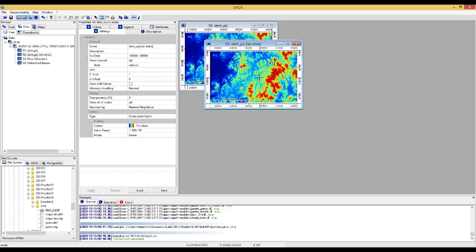If cells with higher elevation surround any cell in a DEM, the flow gets trapped in that cell and cannot go downstream. The Fill Sinks tool modifies the elevation values to eliminate this problem. The main function of this tool is to remove imperfections in the DEM to enable the flow to move downstream.